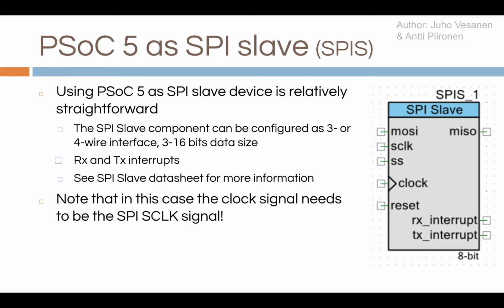The Raspberry Pi does not have an A to D converter. PSoC5 does, and it can also be used with an analog multiplexer with 8 channels. So how about making an A to D converter for Raspberry Pi, which uses an SPI slave interface for communication? Just an idea.